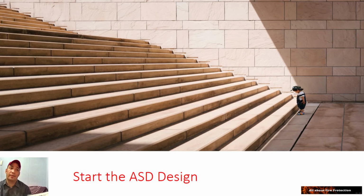Let's take a look at the drawing. There are 6 steps in preparation of design, but before the steps, we should verify first how many voids or concealed space inside the room to be protected. In my example, there are 2 voids. They are room void and floor void. So we will now proceed with the steps in designing of ASD, or which we call aspirating smoke detector.